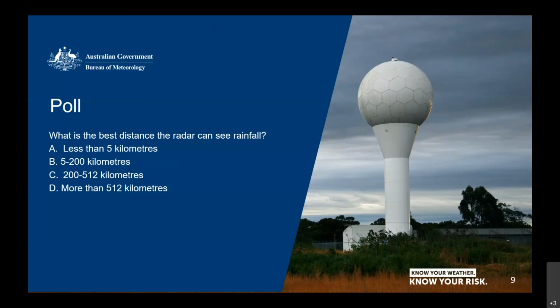So to get the most accuracy out of our radar dish as it's rotating in azimuth and also up and down in elevation, we take the wind load off it, so we put it inside a radome. The radome is round because that's the path that the dish travels in azimuth and elevation. And the dish itself is made out of a bit like fiberglass. It's virtually transparent to the radar beams.